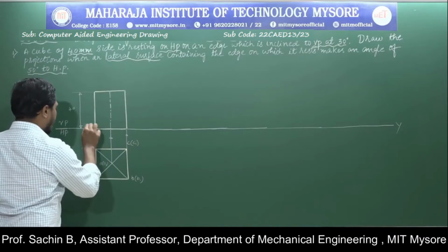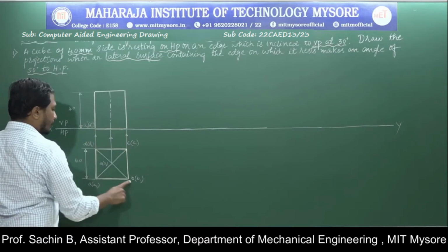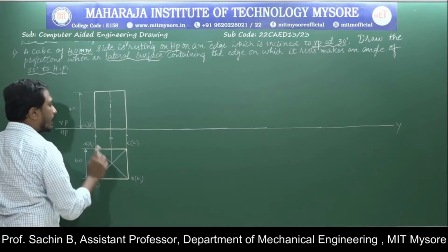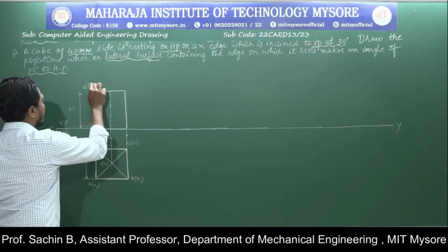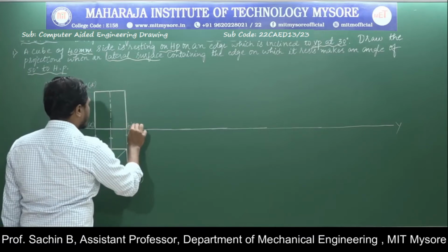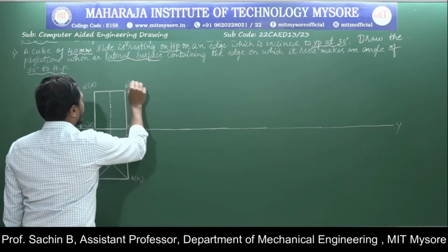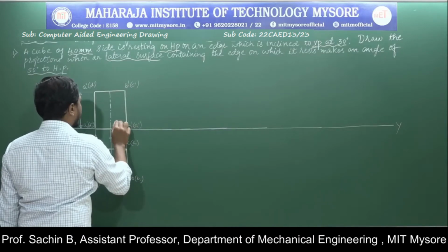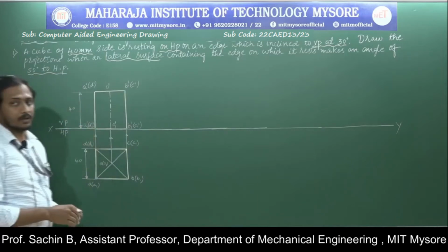Now A1 dash, in bracket D1 dash. In the front view, only this lateral face is visible, that is nothing but A to A1, B to B1. The lateral face is clearly visible for us. Again I will go to the topmost position, A dash to D dash. Again I will come here, B1 dash to C1 dash. Again here B dash to C dash. If I write the O1 dash axis over here, next O dash here. Now this is my front view of the object.